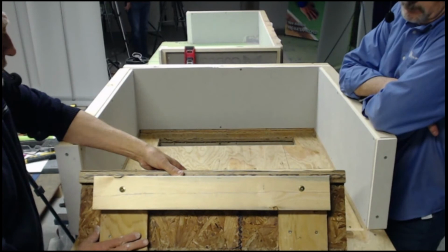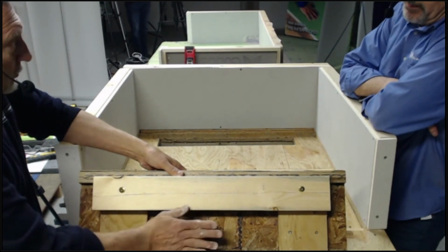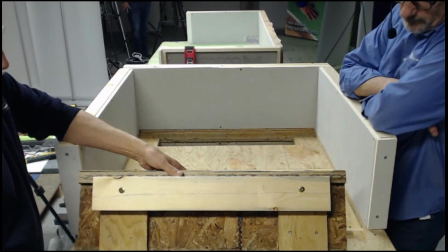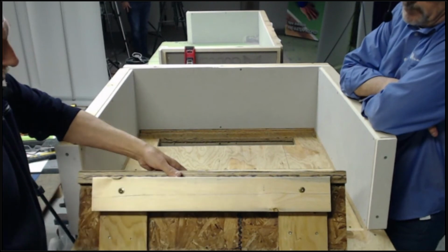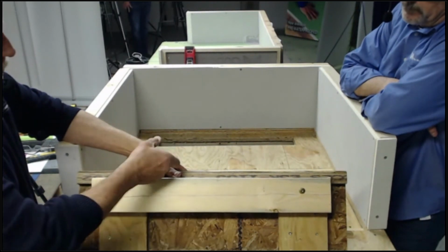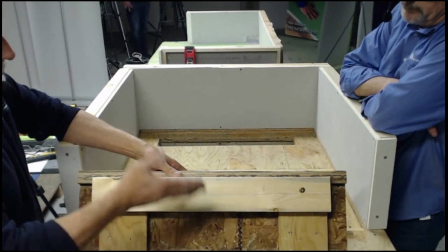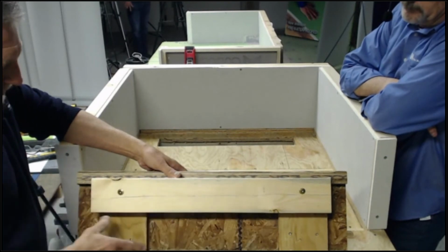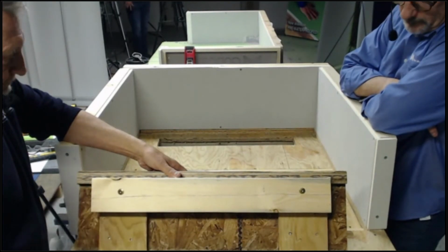plywood or 1 by whatever works well to keep that flush with the I-joist. Trusses, you may have to do the same thing, put some blocking in trusses, because you can have a 2x4, typically top and bottom, which doesn't leave you a lot of room there. So just put some blocking in between there too. Same thing.